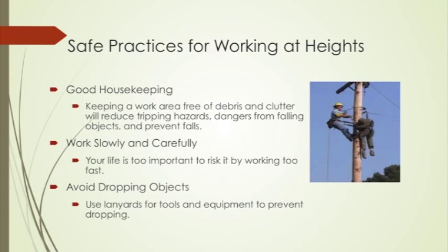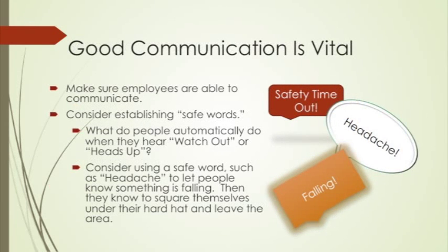While working from heights, use lanyards to raise and lower tools to prevent them from being dropped on others below. It is important that your employees know how to communicate warnings with one another. Safety keywords can prevent accidents by providing valuable time to get out of the way of danger. Take a moment to pause the video and discuss with your employees safety keywords that they already use and other work practices that make a difference.